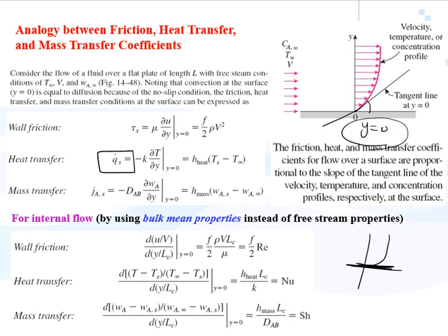So when we are saying that the concentration at the surface is equal to diffusion, we know that the diffusion we can calculate from Fick's law. Okay, so diffusion is equal to mass convection. Similarly, in heat transfer, we can say that conduction is equal to convection.